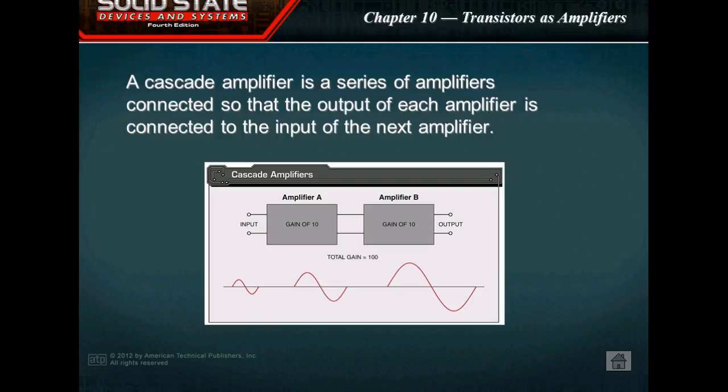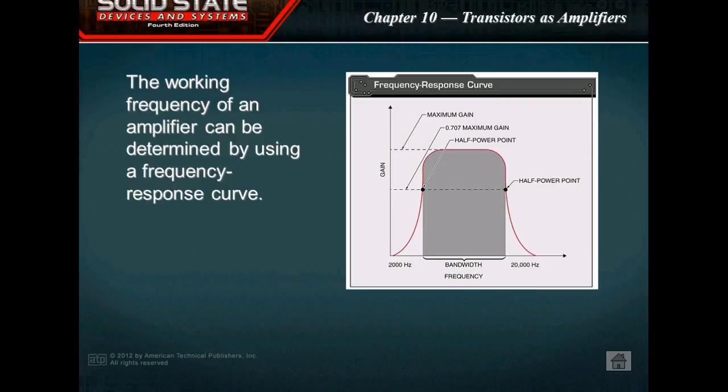So that's what we do: we start off with a very low gain, because most of the time when we have amplifiers, we go through stages. Especially in audio, the more gain you get out of an amplifier, the noisier it is. And also we're dealing with resistances, or what we call impedances, between the amplifiers. And we'll look at that a little bit in this demonstration.